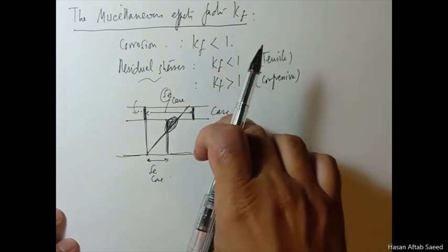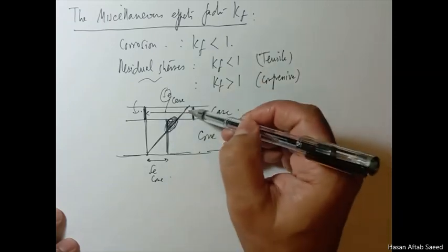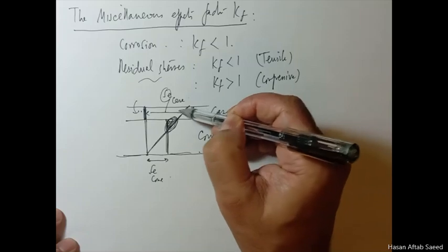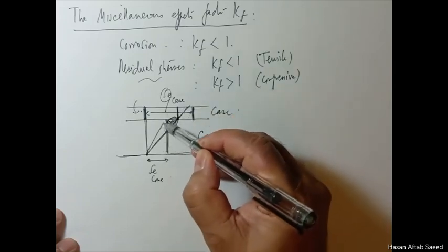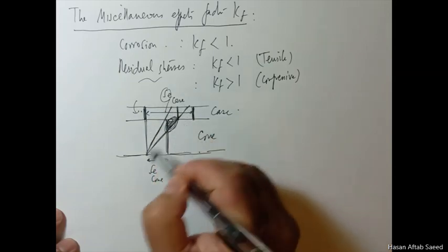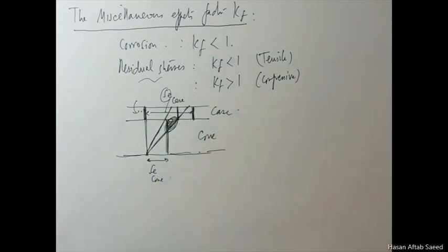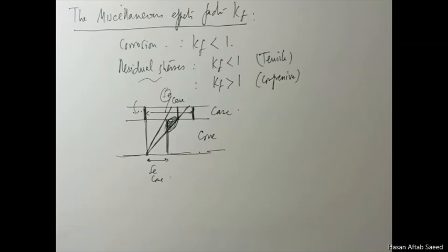For example, if we apply a correction factor in this case, then this becomes this, and we make sure that the stress we are subjecting it to is like this, so it will be safe both in case and in core. There can be many situations where we don't have a separate factor like the size factor, temperature factor or reliability factor.